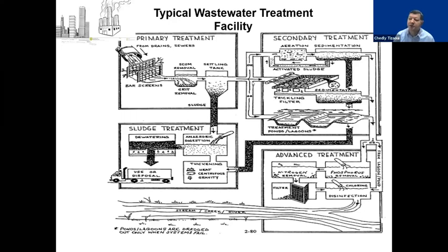So that little fraction of suspended solids plus what is dissolved as organic matter in the wastewater. And that dissolved matter is not going to be removed by any of these unit operations. So you need another unit operation to remove that organic matter. Perhaps if you are a chemical engineer or possibly an environmental engineer, you would say, I'll use a chemical reaction to remove those organics in wastewater.